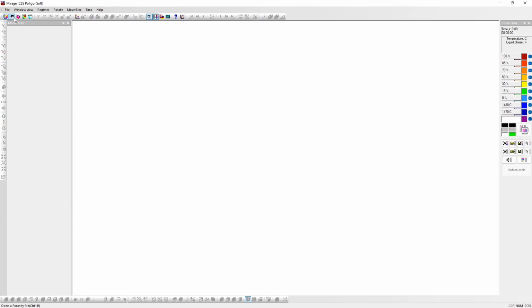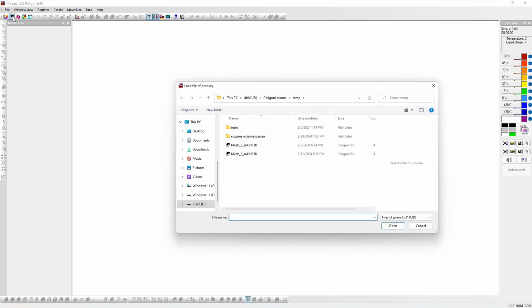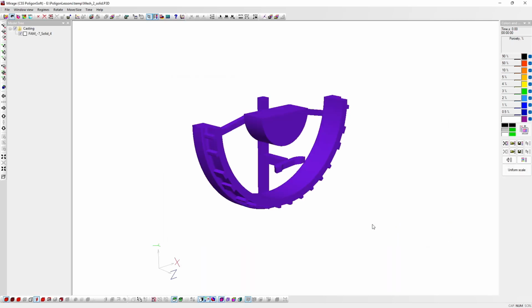Macroporosity is formed due to insufficient feeding, that is, the lack of a necessary volume to compensate for the contraction of the alloy during solidification. Sometimes, the level of porosity can reach 100%, which means the formation of a shrinkage cavity. Microporosity is formed in the last stages of the casting solidification, when the gravitational flow of the molten metal through the dendritic network is no longer possible, and filtration flow becomes the only feeding mechanism. In the end, the data on macro and microporosity are combined, and we can see them as a porosity scale in percentage from 0 to 100.